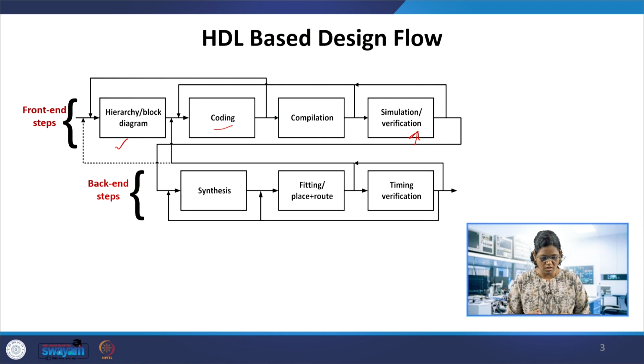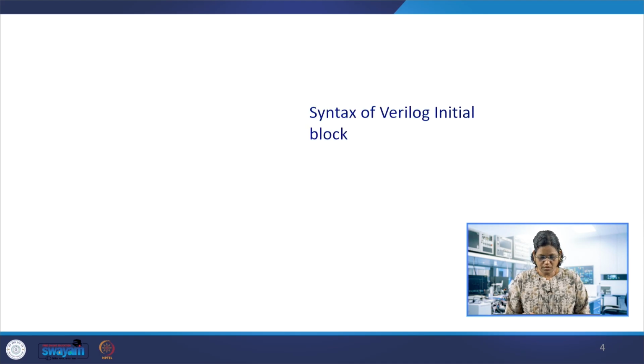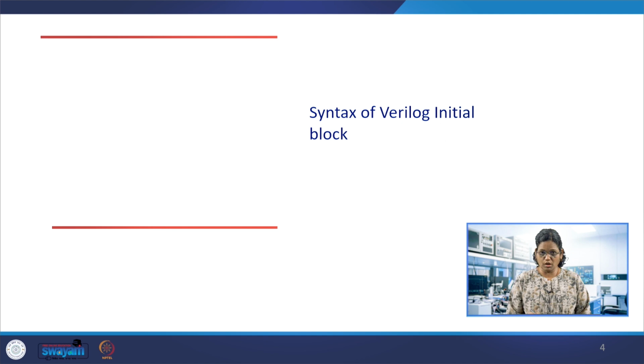Coming to the syntax of the Verilog initial block, this is important to know because the initial block is often used in the test bench. In the previous examples also you must have seen that the test bench we had written had initial blocks. The initial block syntax is the keyword initial and then a procedural statement, if there is only one statement.